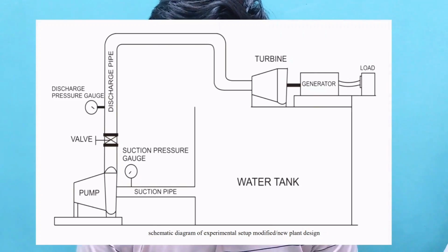Now how can we modify the Pelton wheel design so that it can work at a low head using potential energy? The Pelton wheel is generally used for high head and low discharge applications, but it can be used for low head also by adding some modification in the design. The splitters are used to increase the efficiency of the outlet of the water jet so that water can leave the bucket with minimum velocity, which is theoretically assumed to tend to zero.